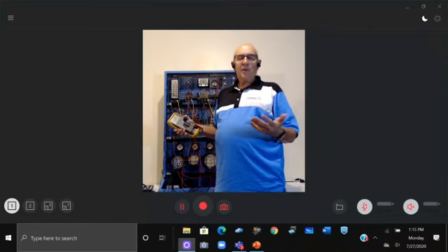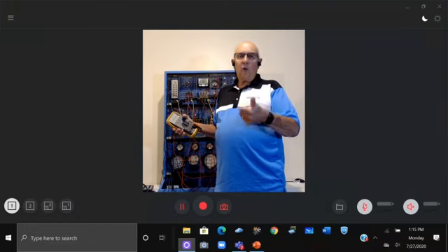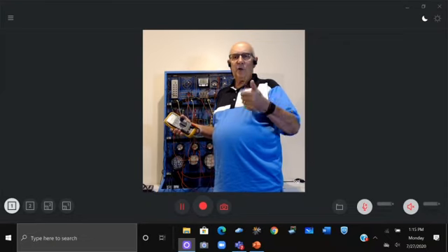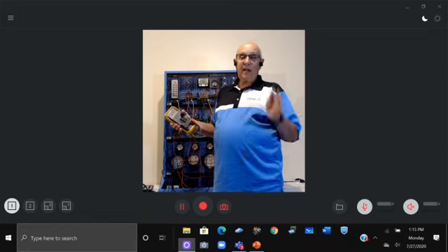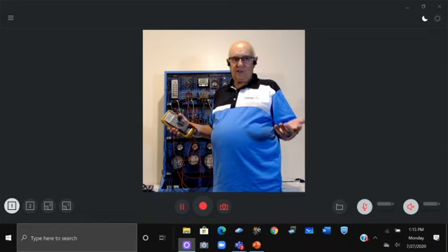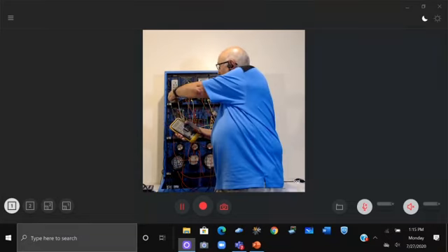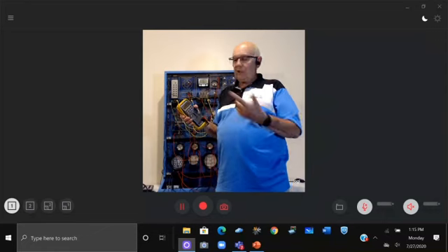So they're in parallel in the circuit. Now, Ohm's law says the total resistance of resistors in a parallel circuit is always going to be lower than the lowest resistance. Or a subset of that is if we have two resistors which are the same resistance, 120, 120, then the resistance value will be 60 ohms.